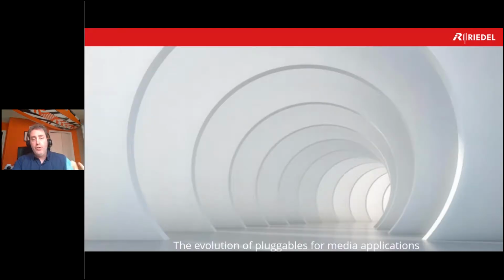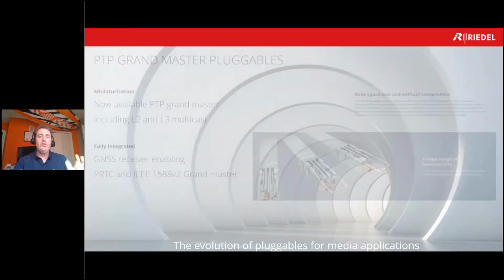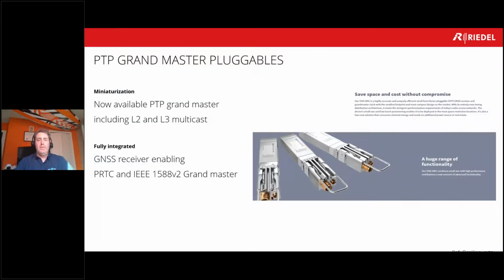First of all, the evolution. There's a couple of vendors that are active in this field. The first one I want to show you is a really interesting one. It's Oscilloquartz, as you can see in my reference in my slide. Let's say you are in a remote production environment or a small studio or even a lab, and you say, I need a PTP to black burst. Of course, in a real studio, real environment, you want to get a good SPG or two big grandmasters, but sometimes these guys will do good for a redundant grandmaster. They're really acting like a grandmaster. They're fully compliant with everything, and they do a decent job.